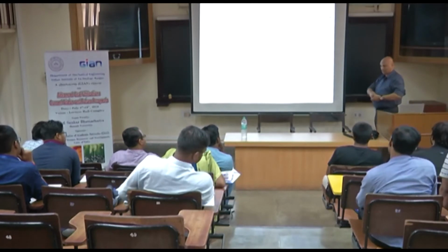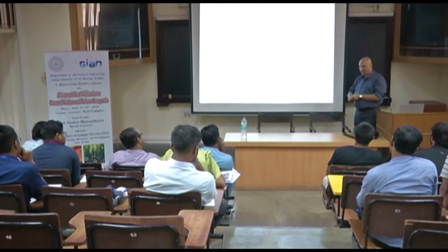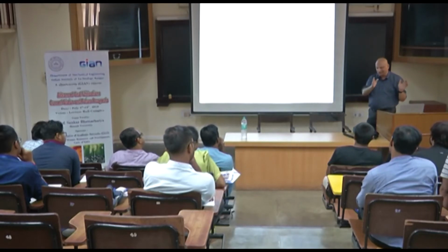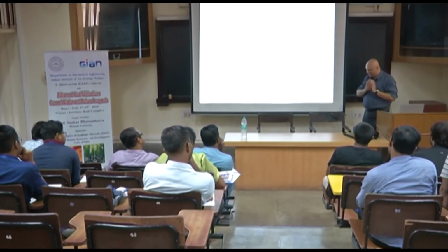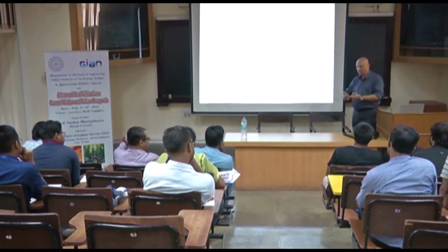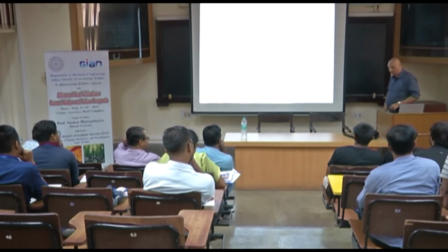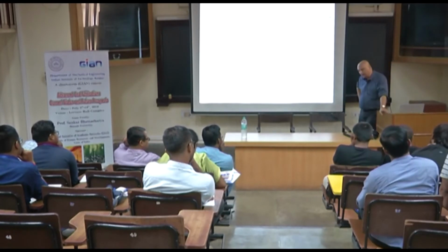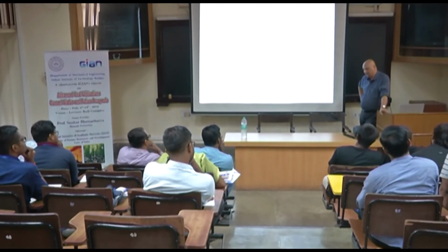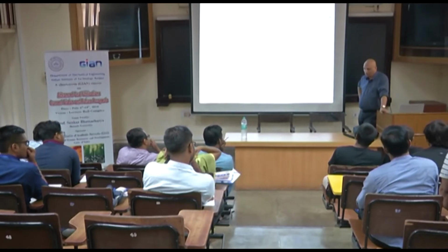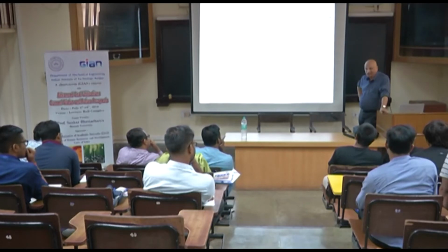Volatiles, I mean the proximate, the ultimate, the ash analysis. If they see that it is all within their experience database, they will go ahead. If they see something completely out of the ordinary, they will ask for more information. In fact, when I was involved with the Angul plant, National Nalco's plant, one of the three bidders actually took a substantial quantity of coal to test it before they put their tender, before they put their bids, sorry.